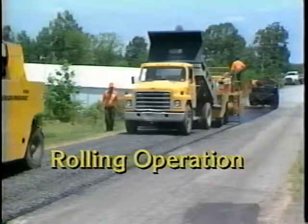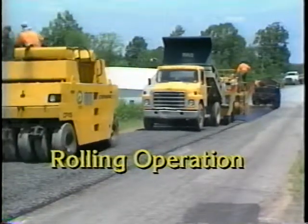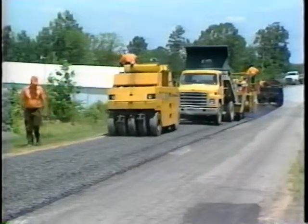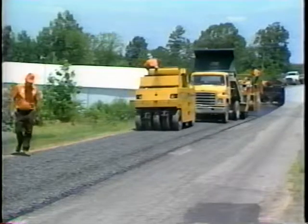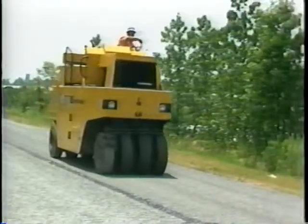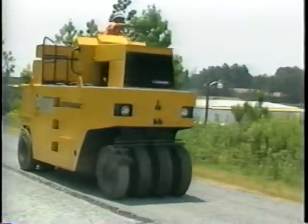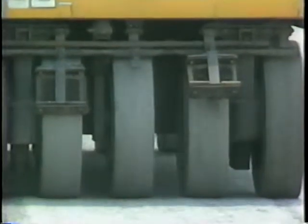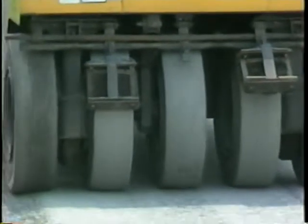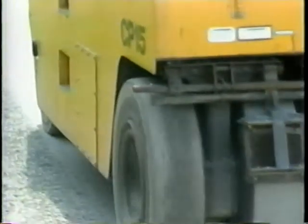Following the aggregate spreader, step number 6 is the rolling operation. The rolling operation proceeds immediately behind the aggregate spreader. A self-propelled, smooth-tread pneumatic-tired roller with a tire pressure of 60 to 90 pounds per square inch is recommended. The pneumatic roller's tires force the aggregate firmly into the asphalt binder.